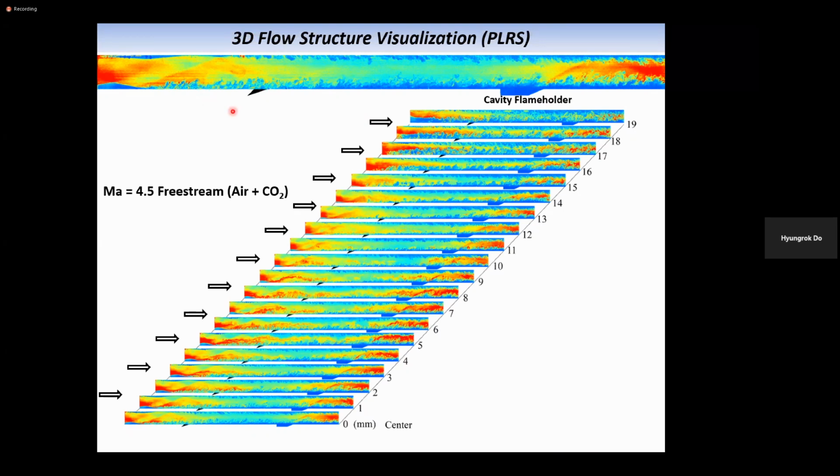So this is a quite nice visualization technique to show you where a shock wave is placed, where the pressure is increased, where the turbulent boundary layer develops, and where the shock wave interacts. Okay, and this flow is becoming turbulent, and the flow speed is so high, and the Reynolds number is on the order of millions. So it is quite a fast and three-dimensional flow.